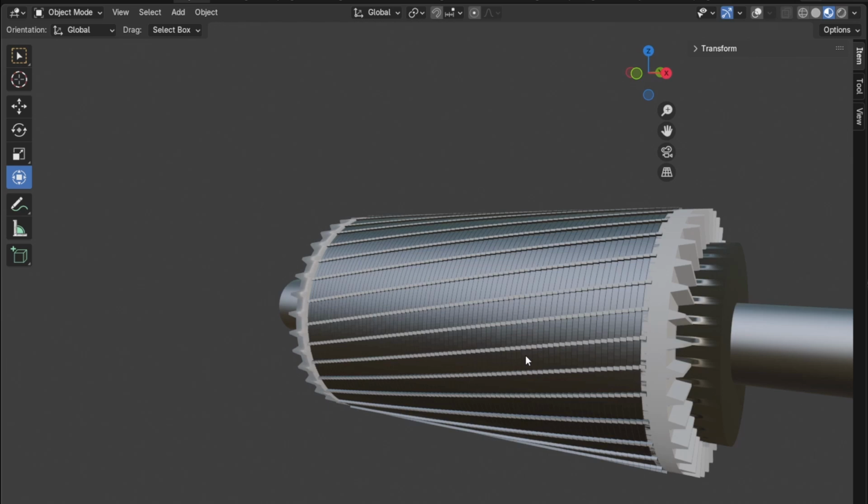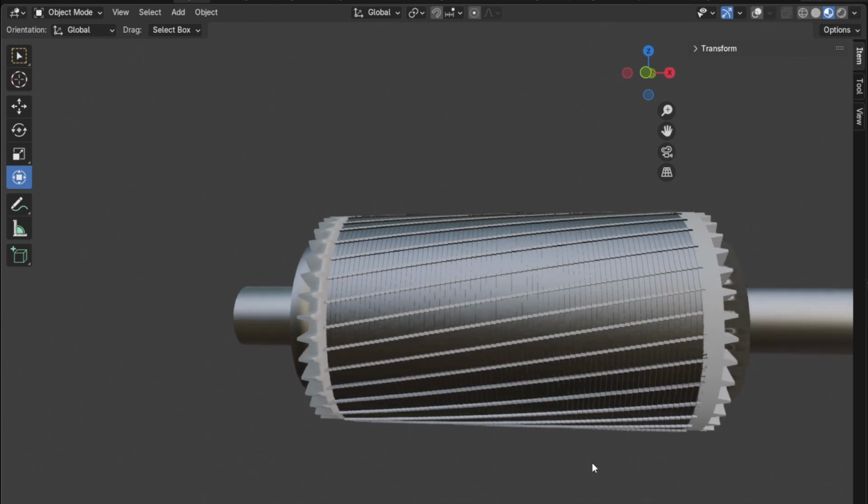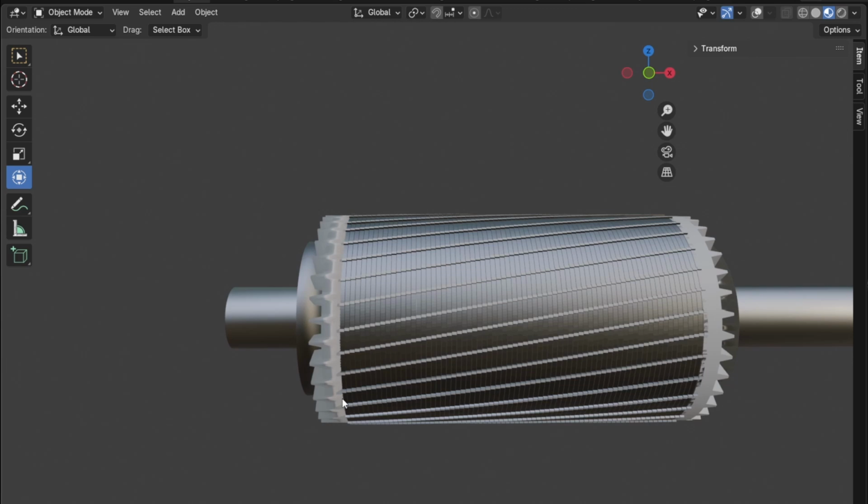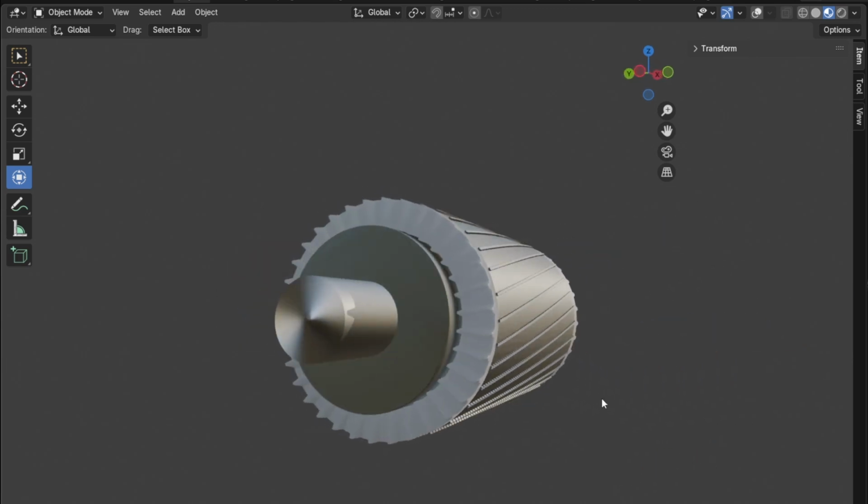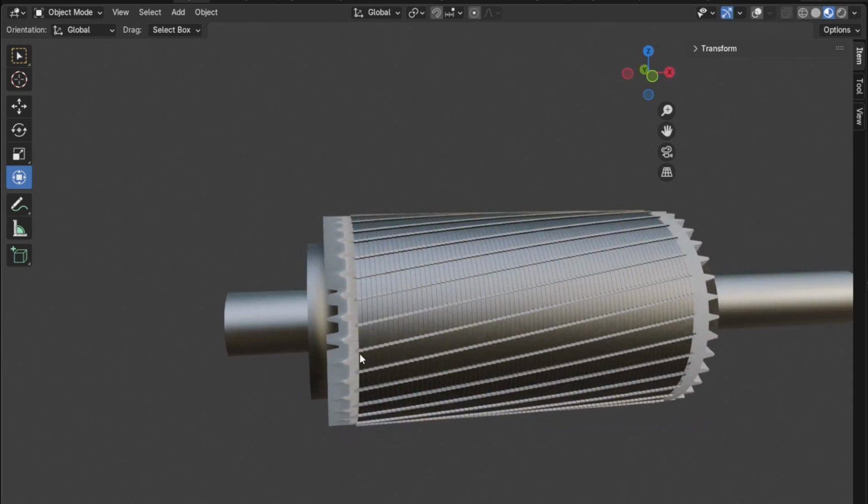But what I want to stress here with this rotor is that it is not magnetic in the slightest. It's not a permanent magnet at all. If you look at this rotor, you have these two things right here. These light sections on the ends are called end rings, and they are solid. They extend beyond this, and it's basically a solid piece of conductive metal. And then you have these bars. These bars connect these two end rings, and they short each side of the end rings together.